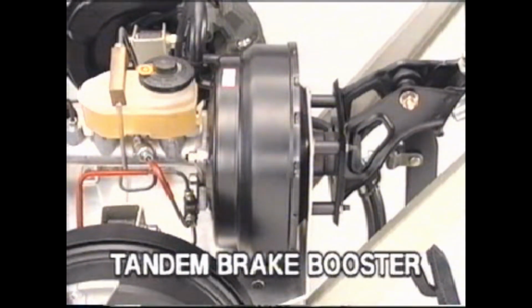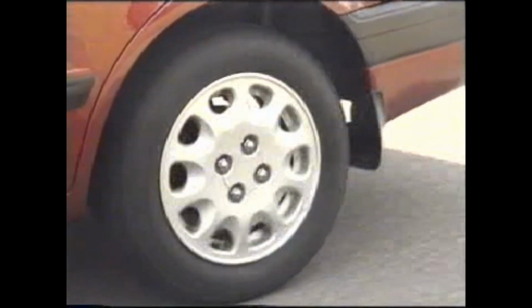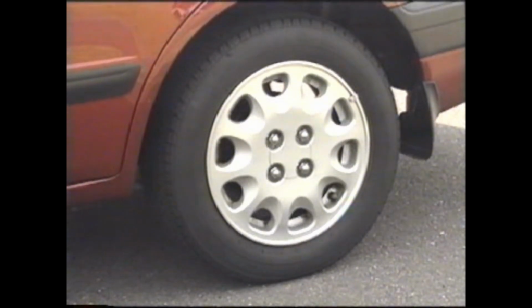The tandem-type brake booster is a compact and extremely powerful unit having 2 vacuum chambers. The force enlarged by the pedal's principle of the lever and the difference in pressure of the brake booster is converted to hydraulic pressure in the master cylinder and is transmitted to individual wheels. The substance transmitting the pressure is the brake fluid.